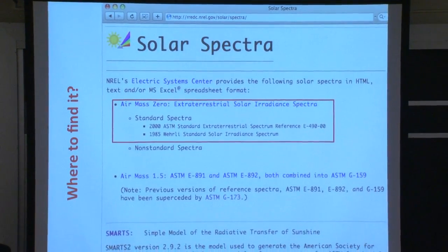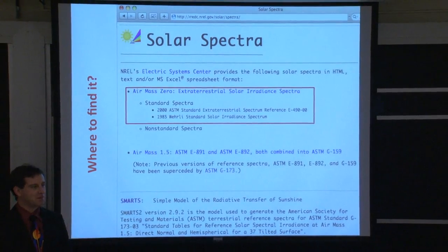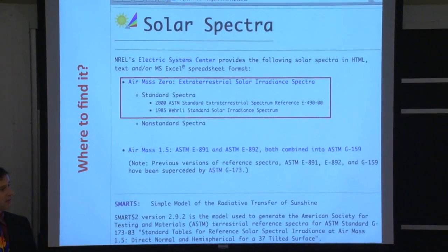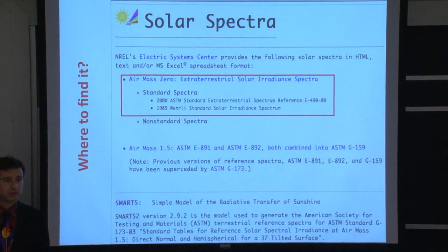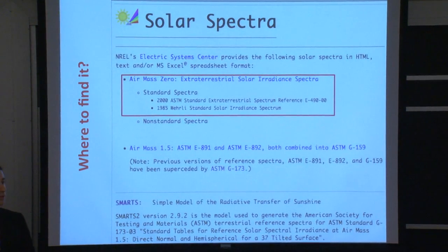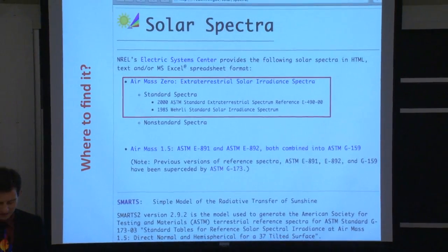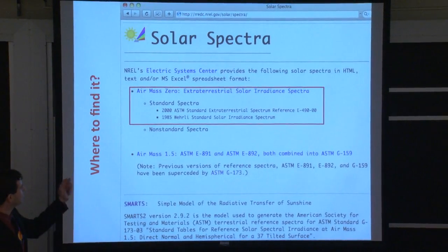So in one scenario, you could say, well, let me just go outside and measure the solar spectrum. If you go outside today, it's kind of cloudy. The spectrum would look very different than tomorrow. And so it'd be very difficult for you to compare the performance of your device against somebody who might be in Germany, or somebody who might be in Finland, or somebody who might be in Brazil. So that's why we come up with a standard reference solar spectrum. And it's shown right here.